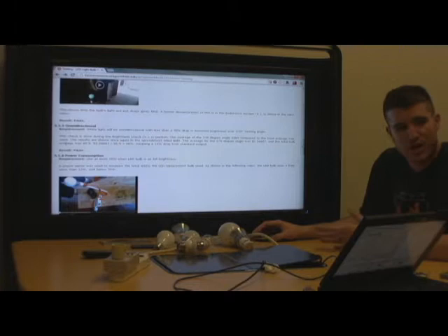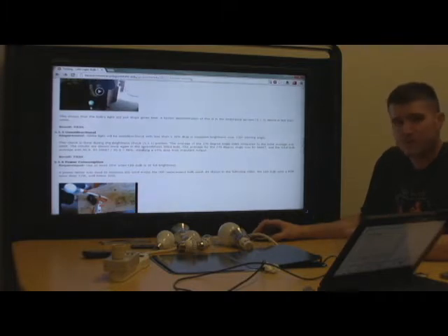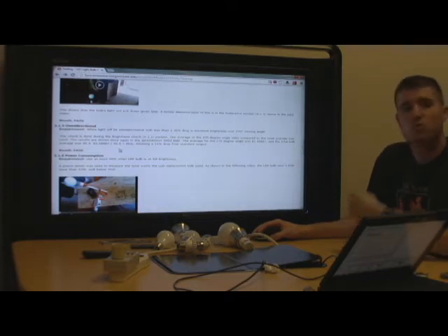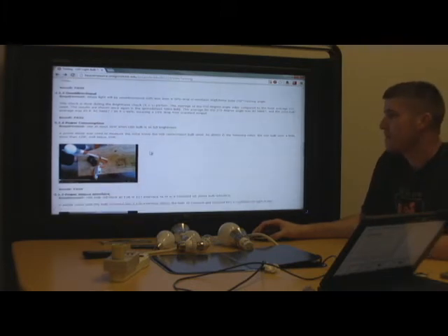Omnidirectional check. This was actually checked during the brightness check, using the same numbers from the spreadsheet. Once we did the calculations, we found that the average for the 270-degree angles was 82.566, and the total for the bulb was about 95.9. So 82.56 was about 86% of the total. Our requirement was no more than a 30% drop. We only dropped 14%, so that passes.